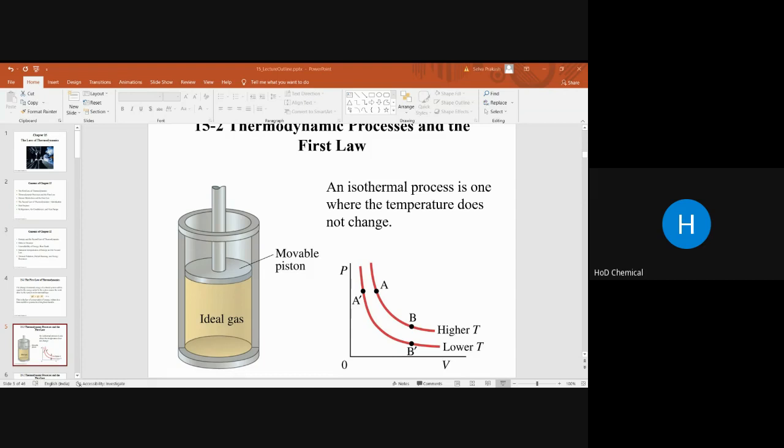For a process where the pressure varies, the work done is the area under the PV curve, which means the pressure and volume curve. Now look at the graph. Several points are denoted for easily understanding the pressure volume curve. The starting point is zero, and the x-axis is, as usual, V. The y-axis value is P.